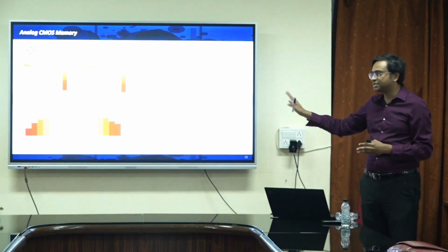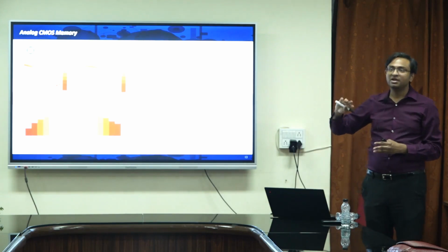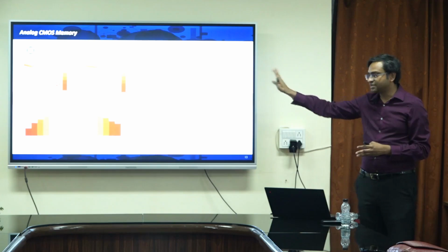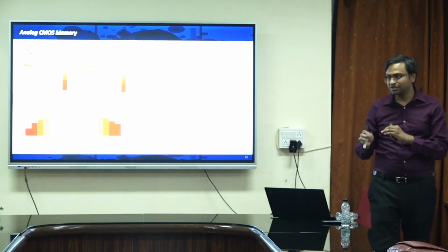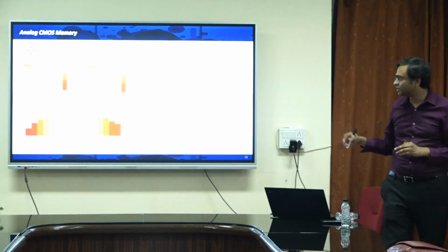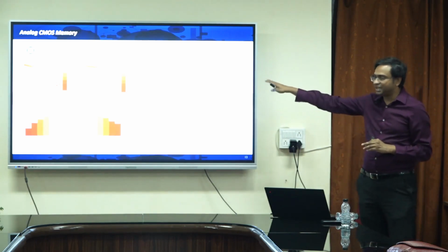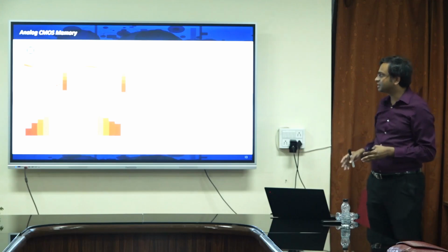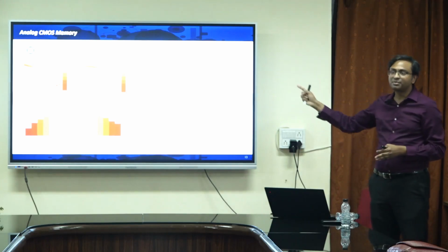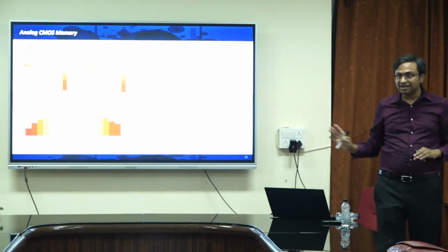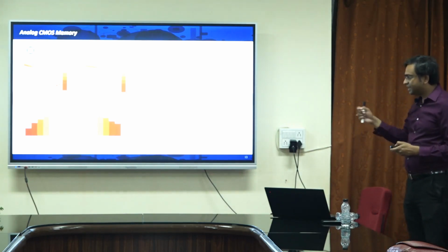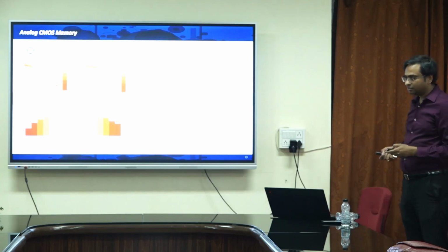So that's why we are showing that it can be applied to both NMOS and PMOS. NMOS is made out of MoS2. The PMOS is made out of tungsten selenide. We did not cover the N-type and P-type FETs in the two other lectures. But at the end of the day, some of you may have seen how an N-type transistor looks like, how a P-type transistor looks like, and I can program and reprogram both the N and P-type transistor. That's the take-home message from this slide. Okay, so that we can integrate memory with logic, for a CMOS logic.